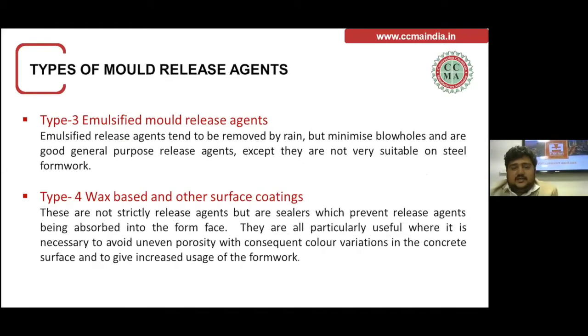The third one is emulsified mold release agent. The minus point in this emulsified system is that if there is rain, it cannot be used because it's water based and the release agent will wash away. But other than that, this gives minimal pinholes or blowholes, and it's a general purpose release agent, except that they are not very suitable on steel formworks.